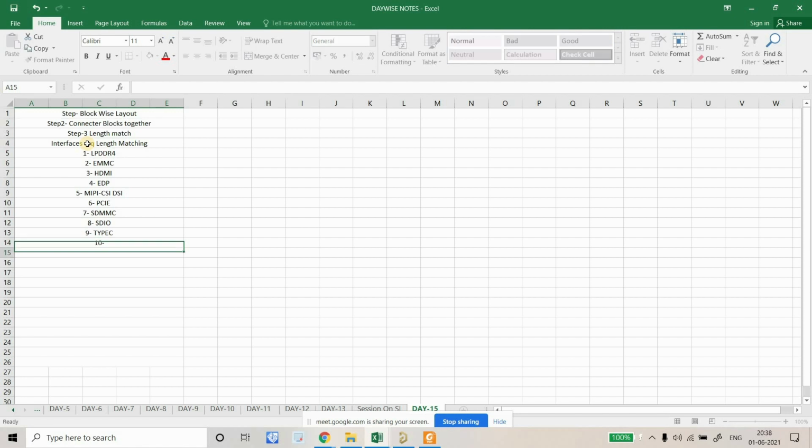After MAC we have one more, that is USB. On USB, I'm saying it should be length matched. I'm talking about the intra-differential pair, so both lines of the differential pair should be length matched for USB, or wherever we are using differential pairs. So 10th will be USB 2.0 and 11th will be SDIO. Oh, SDIO we have done that. Okay, 11th will be MAC.